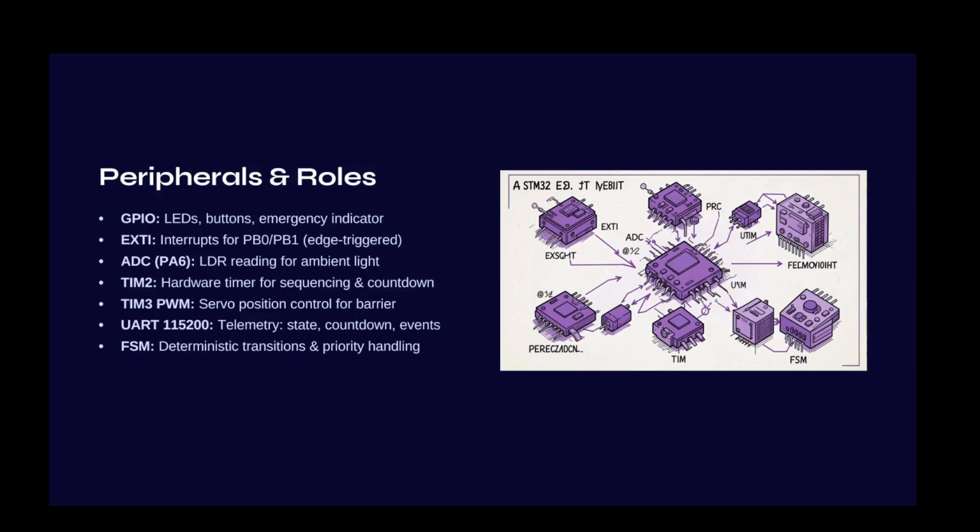EXTI. EXTI stands for External Interrupt. Instead of continuously checking the buttons, the STM32 immediately responds whenever the pedestrian or emergency button is pressed. This made the system much faster and more efficient. Learning interrupts helped me understand real-time event handling.